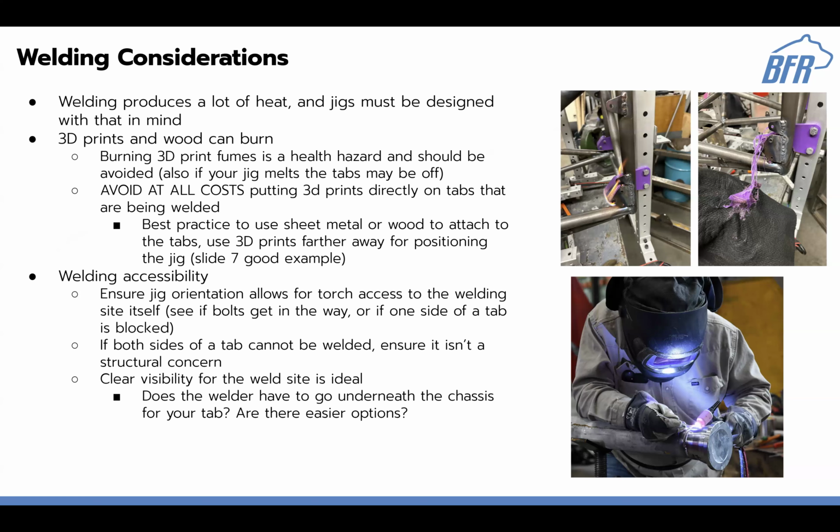We're going to be doing some testing this year to see how little weld perimeter you actually need. So in any case, if you end up seeing that your tab is going to have problems getting the full perimeter welded, just see if it's going to be an issue structurally. But yeah, anything else I'm missing? Try and remember that someone actually does have to weld it. And you can always talk to one of the welders, Josh or Fauna are good examples, people you can talk to, whether or not they think it'll be a problem, like if certain gaps are wide enough.